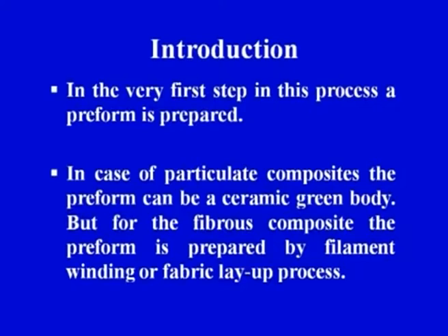It is also important to note that if the reinforcement is particulate, the green body or preform would be different, and if it is a continuous fiber reinforcement, the preform would be of a different shape and form. This clarifies that particulate reinforcement can also be used in directed metal oxidation. So in the case of a particulate composite, the preform can be a ceramic green body.